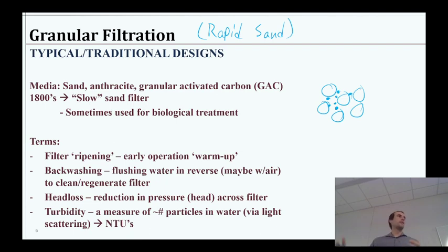It takes a few minutes, maybe 15 minutes, of operation before things settle in and start removing well. So that's what we call ripening. That's kind of a warm-up phase, and it's pretty important that we do that every time we backwash.